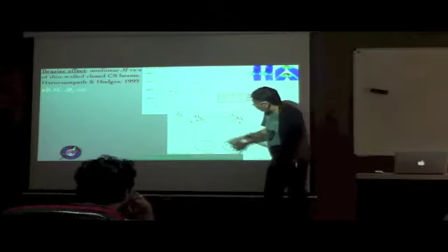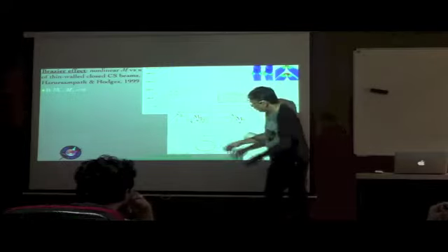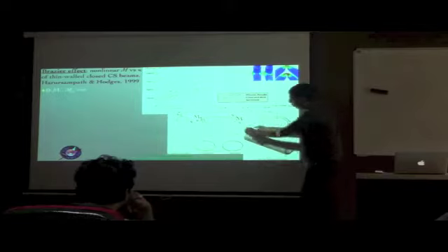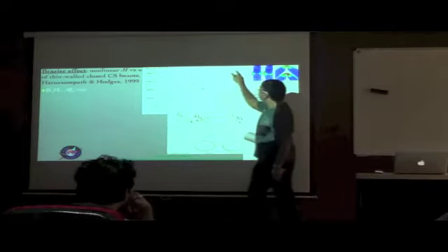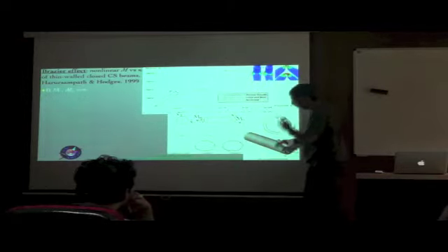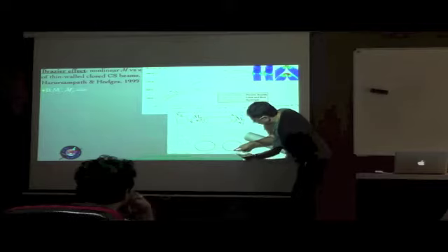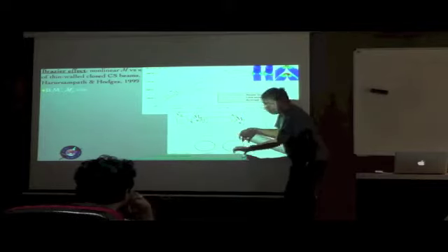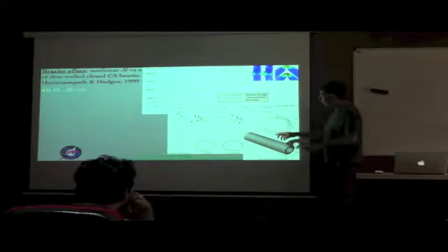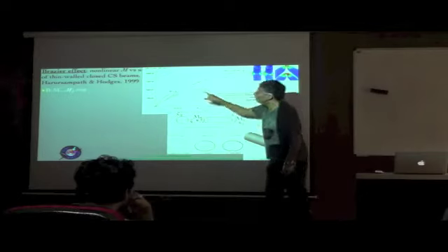And then when there is a small initial curvature, you see that there is a small amount of flattening which takes place. Once you start increasing that curvature beyond the limit for that particular material and geometric layup, you see that a kink forms, and that's when the instability actually happens. This is the initial stage, and then eventually it starts going rapidly.